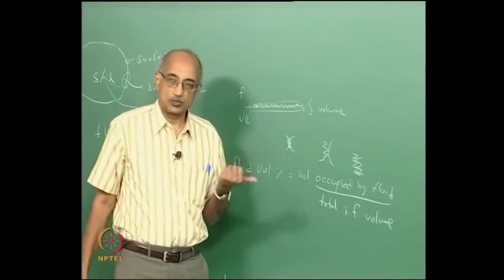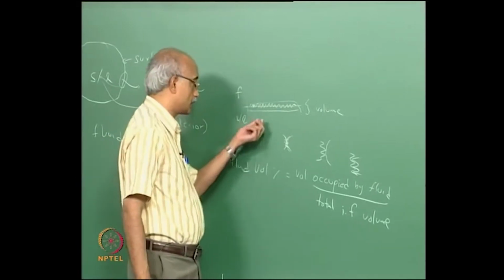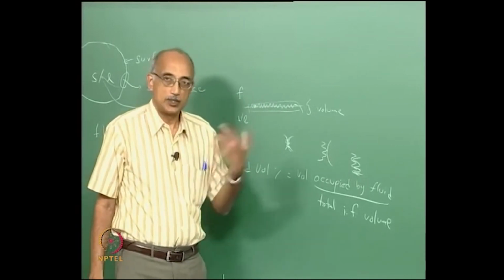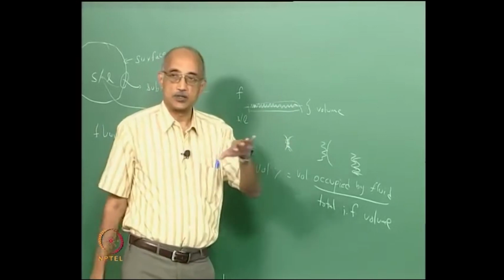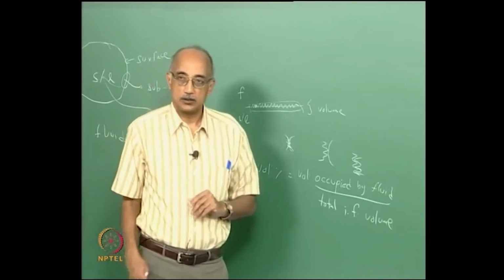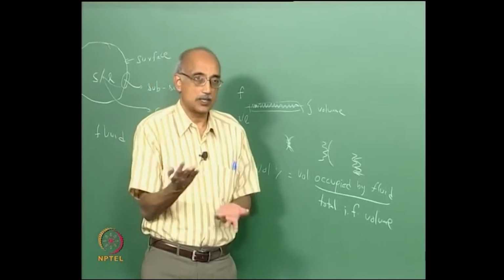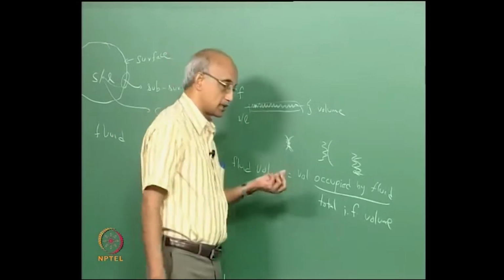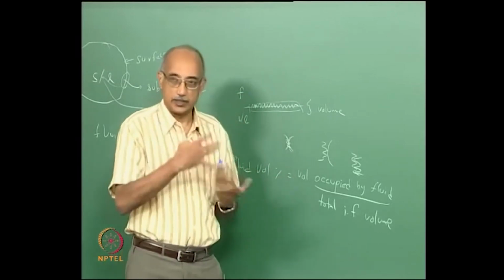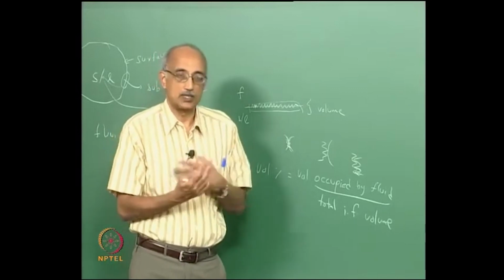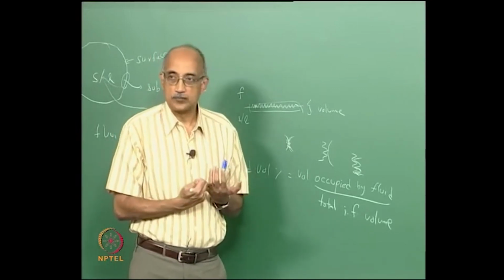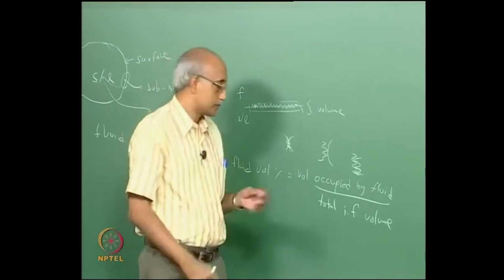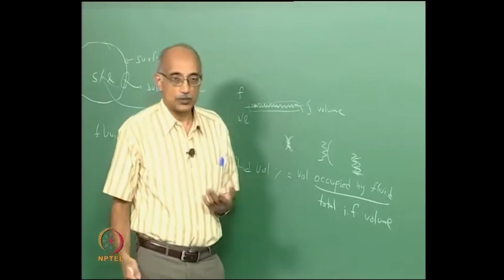The higher this volume percentage, the more the properties of the surface are going to reflect the properties of the fluid. In the extreme case, if the entire surface is inundated with the fluid, then the particle surface will essentially behave just like the fluid, right? Or in the other extreme case, if the particle is such that it repels the fluid that it's suspended in, so that the fluid is not able to wet the particle or be absorbed by it, then this volume percentage is going to approach 0.